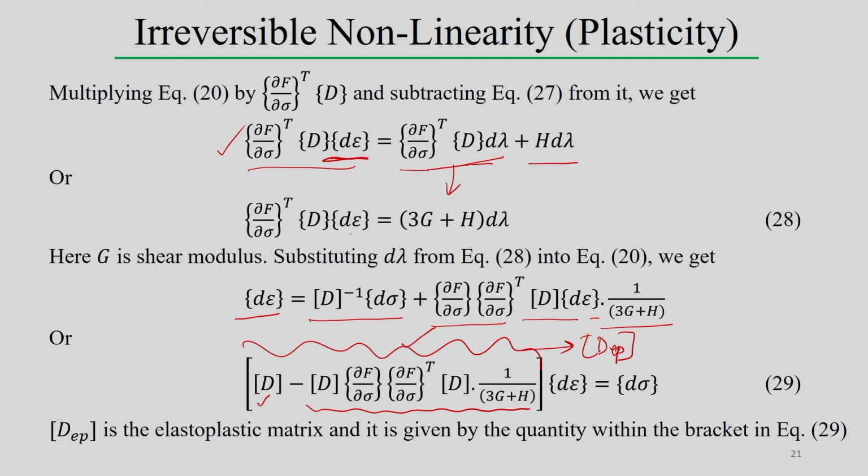So, if we assume the material model follows some sort of elastoplastic deformation in the thermomechanical analysis, then we can construct this DEP matrix. Depending upon the yield point or yield criteria, we can decide which part goes through only the elastic deformation. In that case we use only the elastic matrix DE, and for the part associated with plastic deformation, we use the DEP.